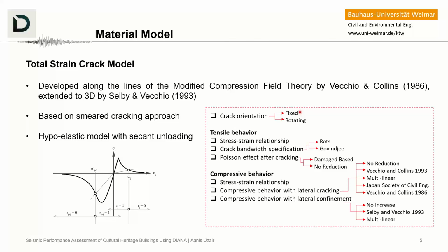So when you are dealing with material models that are highly unknown, or where you don't know the material properties, and you want to make a global analysis without looking into the local mechanisms, or too much into the detail of the propagation of crack, it is always a better idea to go with the rotating crack concept, because then you are underestimating capacity rather than overestimating capacity.